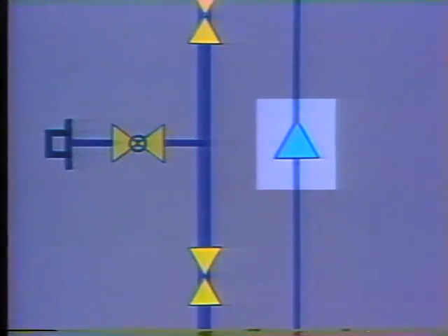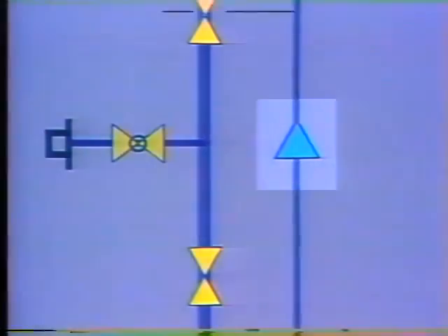There are 4 pieces of information that can quickly show you the flow paths through the system. The most obvious of these pieces of information are the flow arrows. All too often, however, you find prints that don't have flow arrows, like this, but there are still other indications of flow. For instance, pumps and compressors take a suction from one direction and discharge to another direction.